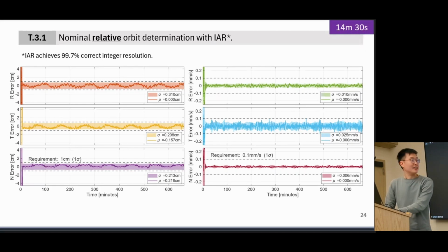Notice that we did inject a very large phase center offset, but the state error remains largely unbiased. This desirable result arises because the filter has sufficient degrees of freedom in the state vector to absorb any residual biases, and any center of mass phase center uncertainty that remains is correctly carried through the considered covariance, so its impact is still accounted for.